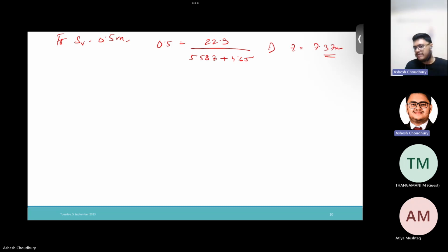That is fine, our height is 7 meters. The height of each block is 1 meter, so for the top three blocks we can put 1 meter spacing, and for the remaining 4 blocks at the bottom we can put 0.5 meter spacing. So that will solve our problem.